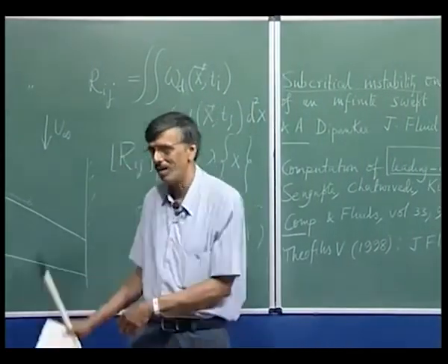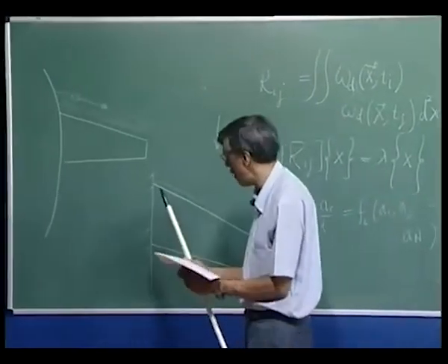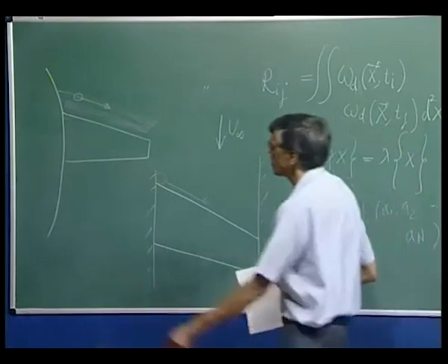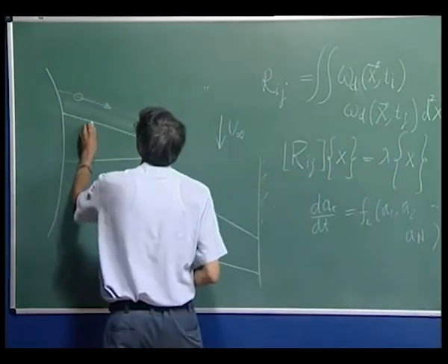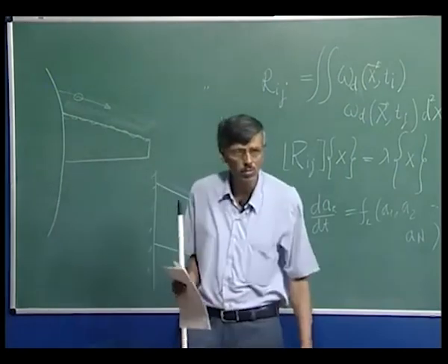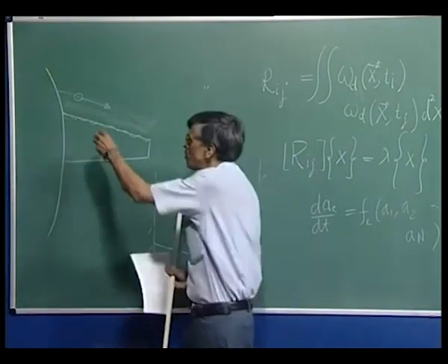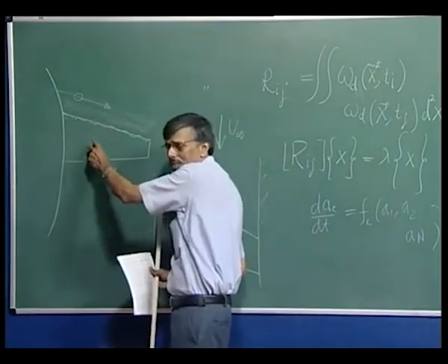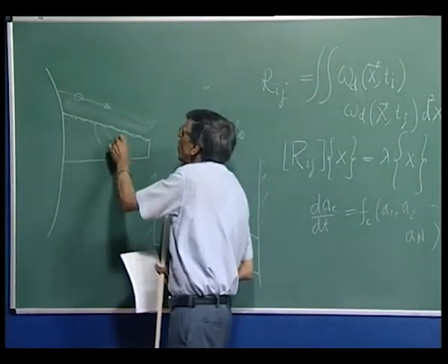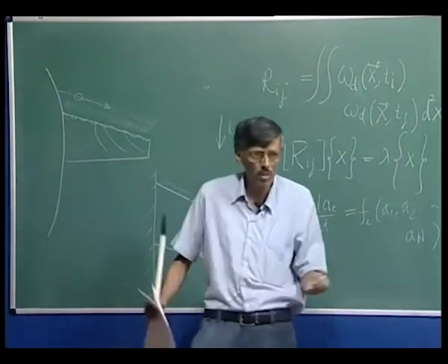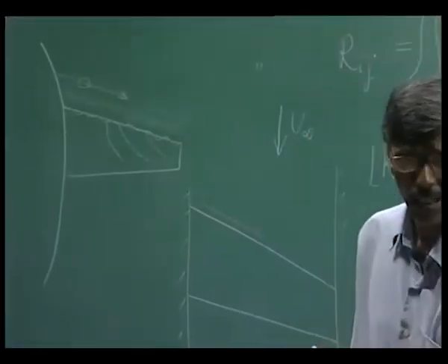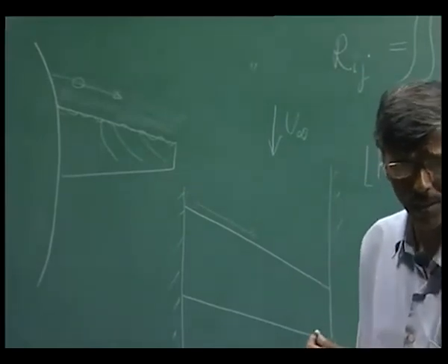subsequently over the wing? So you see, it could so happen that I could have some kind of turbulence set in right here at the leading edge, but that did not go down. That is the second issue. Even if the flow becomes turbulent as it goes along, because it is a swept back wing, the streamlines could go like this, and because of the prevalence of favorable and adverse pressure gradients, those flows may not be turbulent themselves.